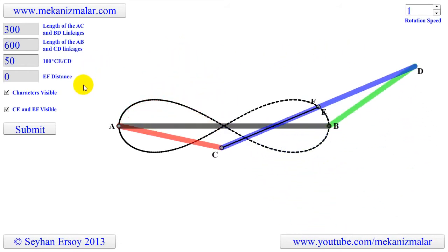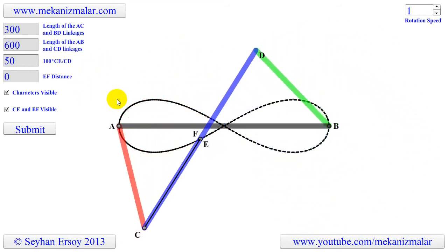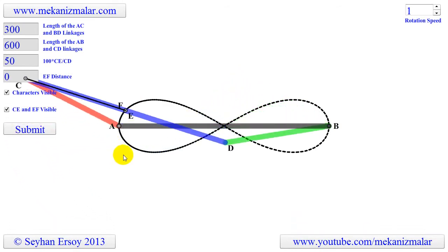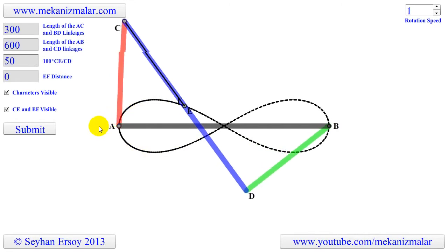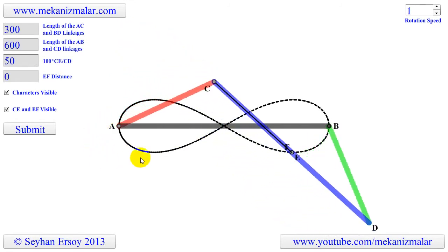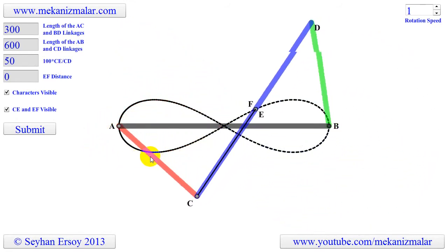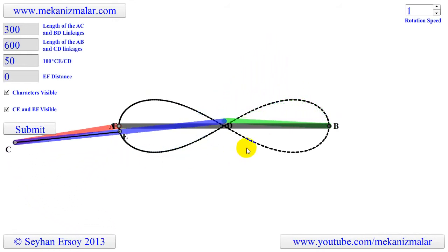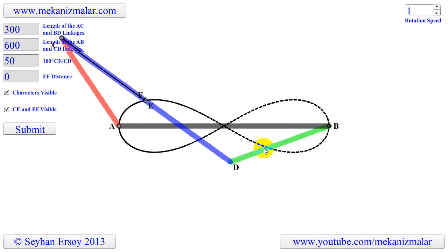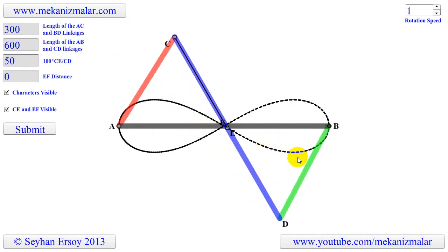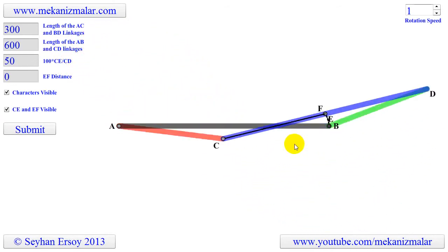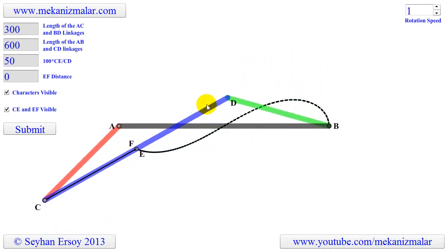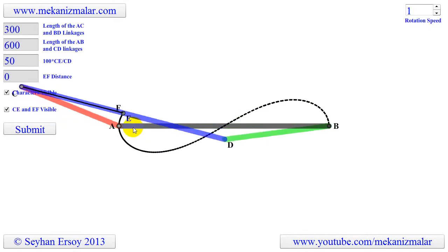Many mechanisms can be broken down into equivalent 4-bar systems. The 4-bar linkages are considered to be one of the fundamental mechanisms. In a 4-bar mechanism, the red linkage of the rotating members usually is the driver and is called the crank or driver. The other, the green linkage, usually is called the rocker or follower. The floating blue linkage that connects the crank and the rocker is called the connecting rod, and the fixed black linkage is called the frame.